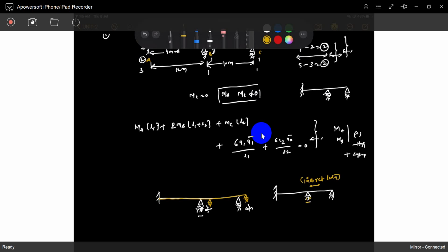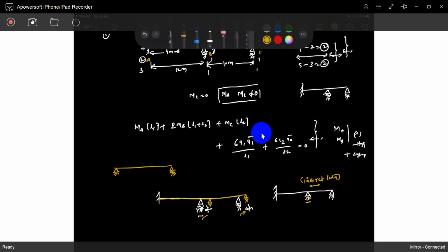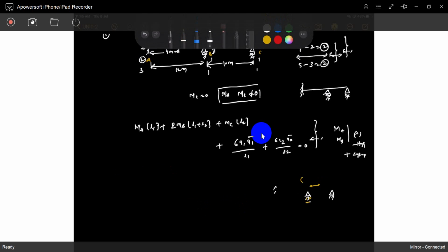So that is the problem. That's why every time roller supports are used. If you take a simply supported beam also, one end is compulsorily a roller. Understood? If it is not a roller, what will happen? If temperature stress is happening, it will expand. If it can't expand, temperature stresses will arise. Understood? So that is one of the students' questions. No need for this in today's topic. We will solve the problem.